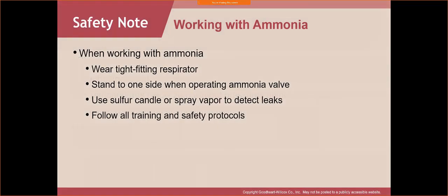So when you're working with ammonia, wear a tight-fitting respirator. Stand to one side when operating the ammonia valve because it is so cold. Use sulfur candle or spray vapor to detect leaks, and follow all training and safety protocols. You may even be wearing an ammonia detector, something that'll trigger. There may even be alarms if there are leaks of ammonia or even other refrigerants for that matter.